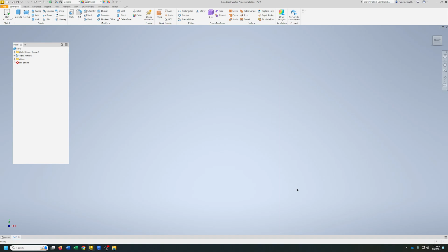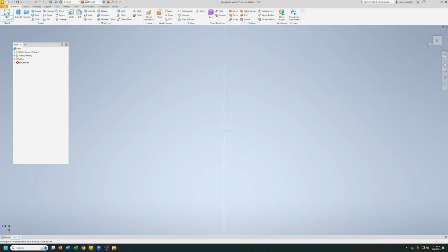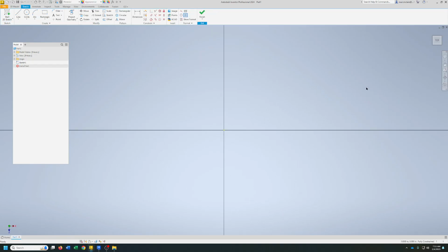If you look in your book, you'll see it's called a pivot latch. Dimensions are in inches. And what we're going to do is start out with a top view, okay? So that means we're going to create sketch, right? And we want to go with this plane right here. This is the XZ plane, okay? So we're going to pick that one. Notice how it flips it sideways, so flip it right up.